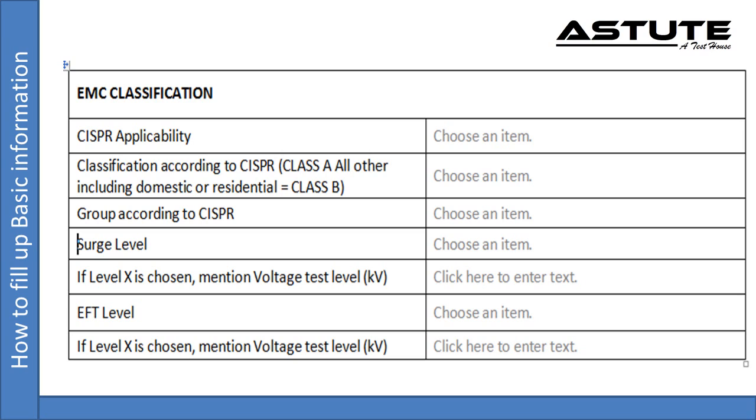The units of the electronic equipment are interconnected by a well-designed earthing system, which is not essentially influenced by the power installation or lightning. The electronic equipment has a dedicated power supply. Surge voltage may not exceed 25 V.